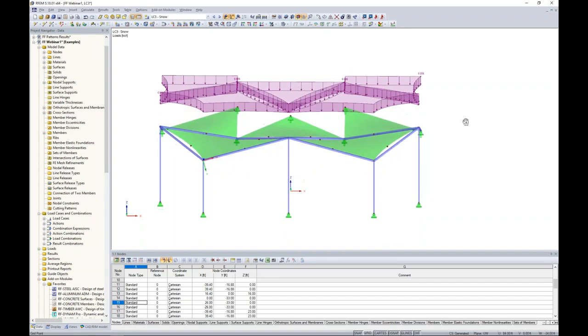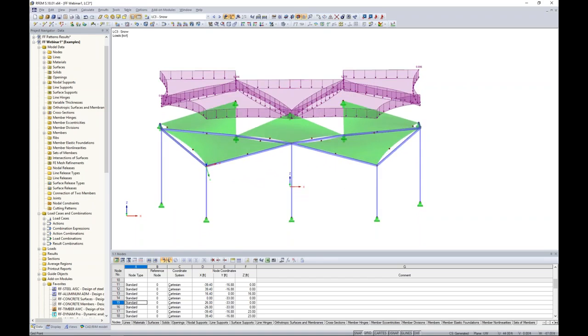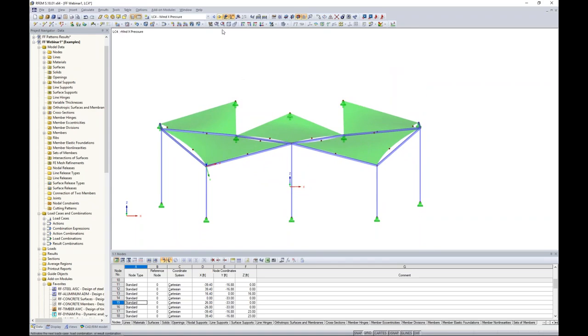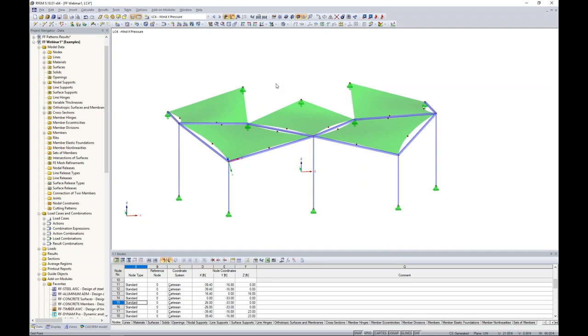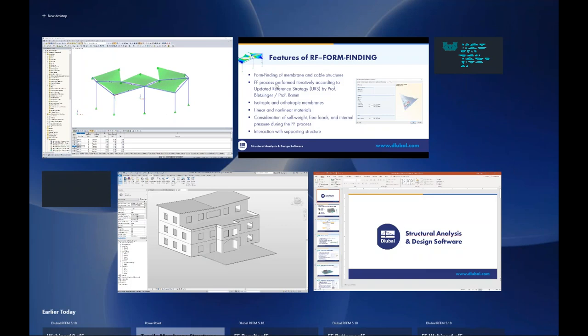The program will account for those angles, but at these areas where our membranes are relatively flat, we're going to see higher snow loads there. So that's the advantage of a projected load. When it comes to our wind loads, according to the ASCE 7, Table 30.11-1, this does address wind loads on attached canopies. So for time's sake, we don't have time to get into this today, but I just want to briefly mention that.